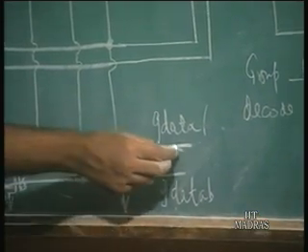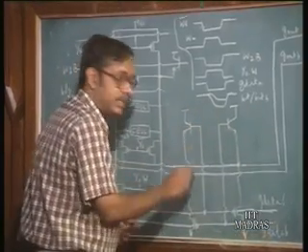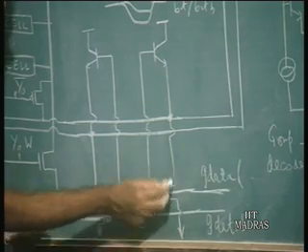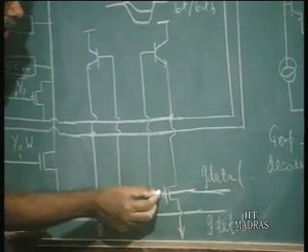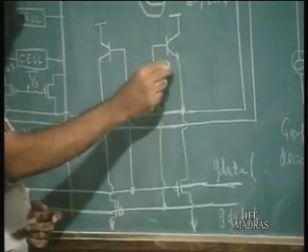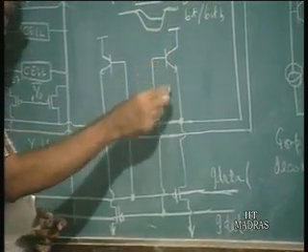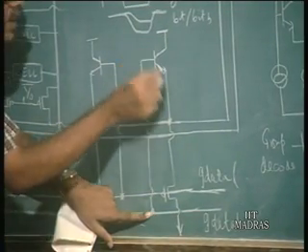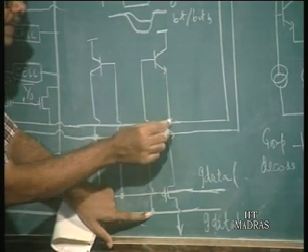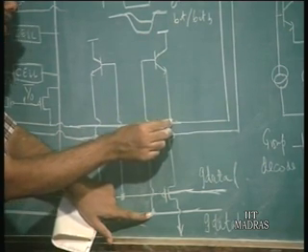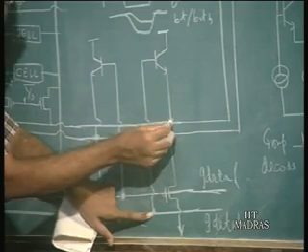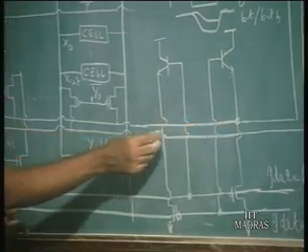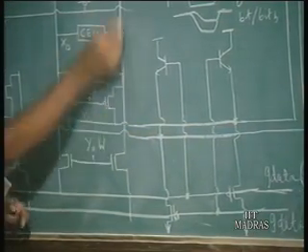All right. Now, what is the need of this part of the circuitry? I will just explain. If this line goes low, this PMOS transistor turns on, because the gate voltage turns low, and so this bipolar transistor turns on. The other line is at VCC high, so there is going to be a VBE drop across this transistor, and the emitter voltage of this bipolar transistor is going to be nothing but VCC minus VBE. This voltage is now available through this pass transistor on the other line.